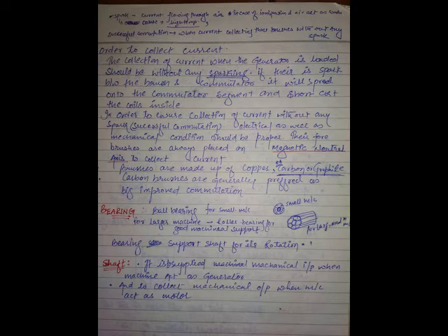What is the voltage induced in this coil at any instant? Let us say here maximum. You know, positions 3 and 7 have maximum induced EMF. Positions 1 and 5 have 0. Remember that? So this is position 1 and 5, and this is position 3 and 7.